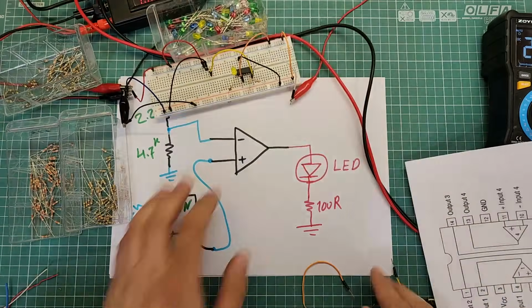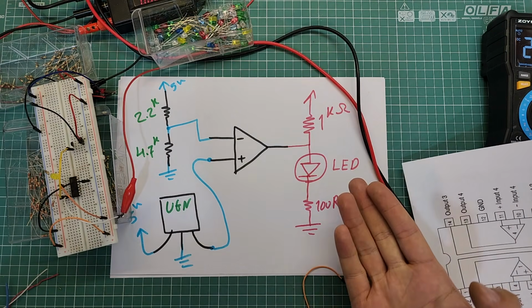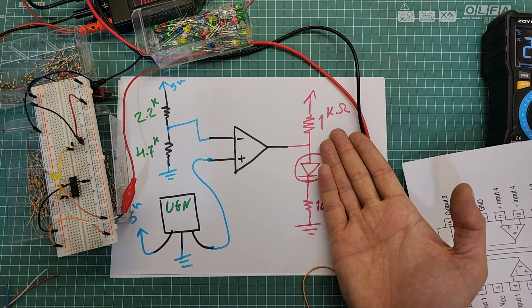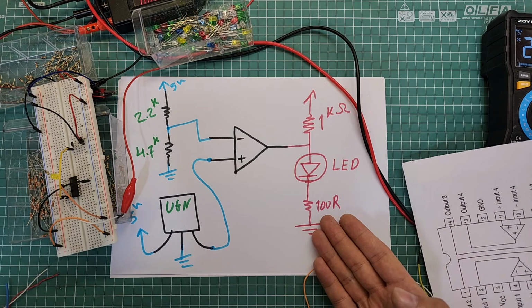The main difference between LM339 and general purpose op-amp ICs is in their output form, which is digital open collector and cannot produce analog voltages, in contrast to general purpose op-amps which can produce analog voltages. So I decided to use this IC as a comparator because it is specialized to be used as a comparator. The output of this IC is open collector, so I have to put a 1 kilo ohm pull-up resistor here. The value of this resistor is not important because it just affects the brightness of the LED.